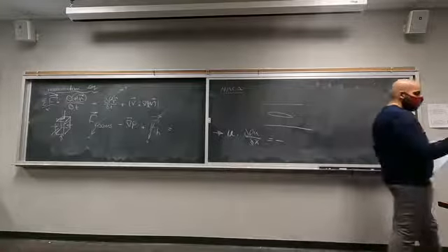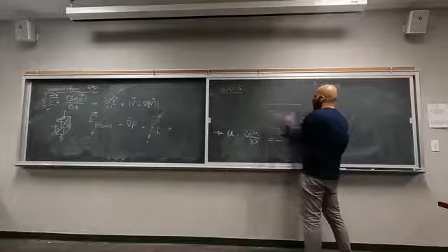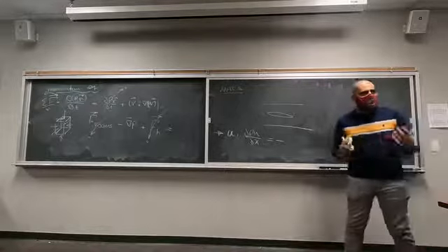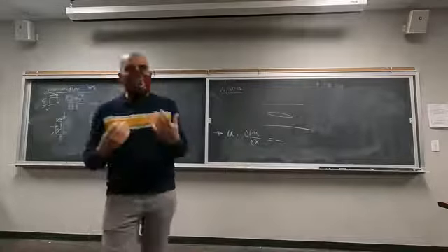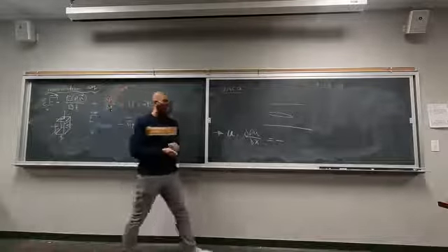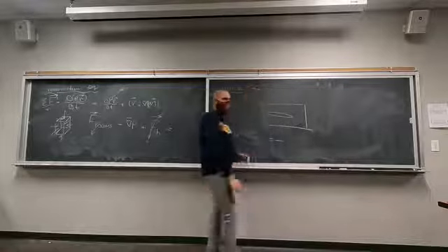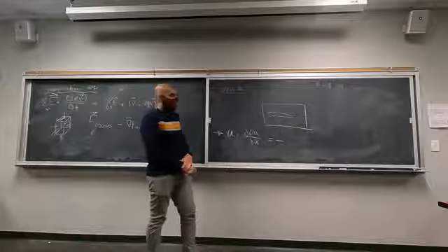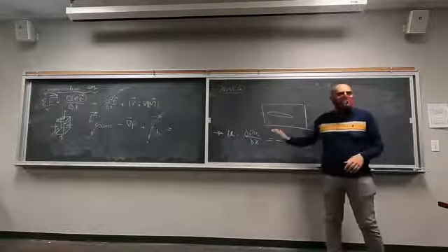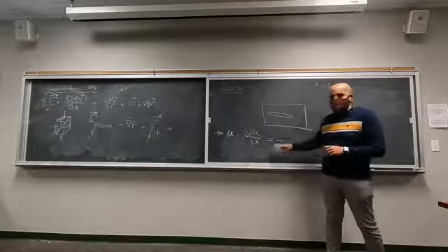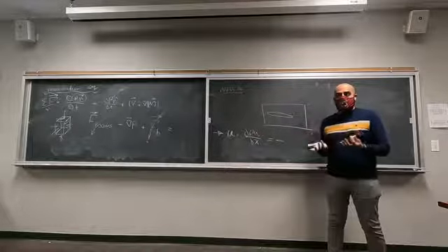So to calculate drag, to calculate the forces that are being applied to this, we removed all of the complexities, all of the problems, and it boiled down to two variables. If we can come up with a way to get the velocity profile here at the inlet of the wind tunnel and the velocity profile here at the outlet of the wind tunnel, and then subtract the two, you are going to find the momentum that has been lost through this equation, right? And that momentum loss is essentially your drag. Does this make sense?